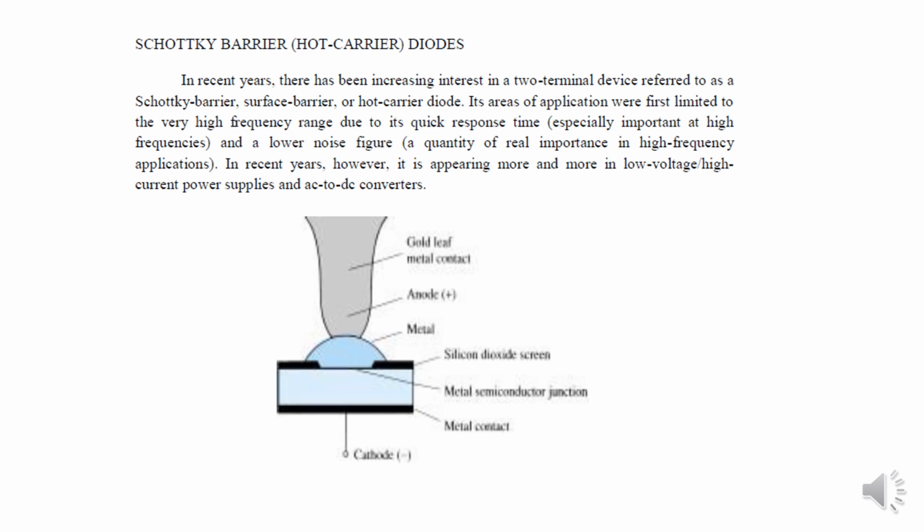Schottky diodes result in a more uniform junction region and a high level of ruggedness. In both materials, the electrons are the majority carriers. In the metal, the level of majority carriers is insufficient, and when the materials are joined, the electrons in the N-type silicon semiconductor material immediately flow into the adjoining metal, establishing a heavy flow of majority carriers.